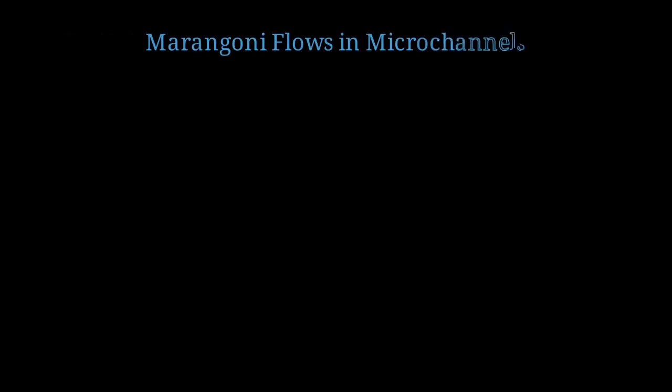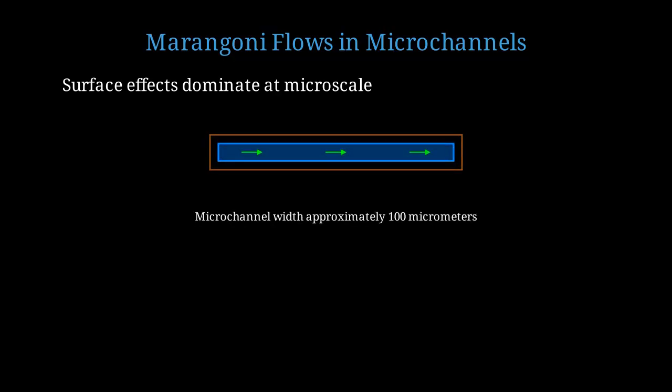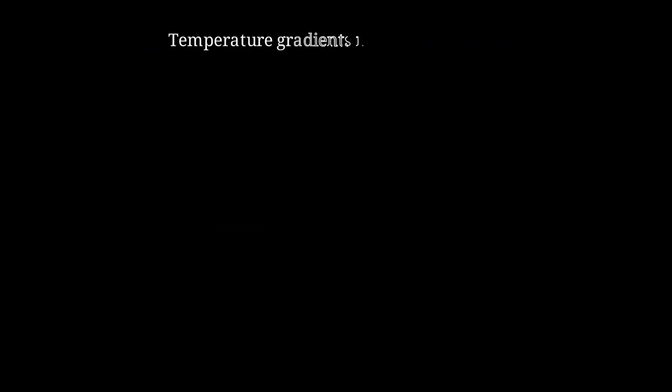Now let's consider Marangoni flows in confined geometries like microchannels, which are crucial for lab-on-a-chip devices. At the microscale, surface-to-volume ratios are enormous, so surface effects like Marangoni flows become much more important than in macroscopic systems. In a microchannel with a width of 100 micrometers or less, even tiny temperature variations or surfactant gradients can drive significant flows. Researchers can use focused laser beams to create localized heating spots in microchannels.